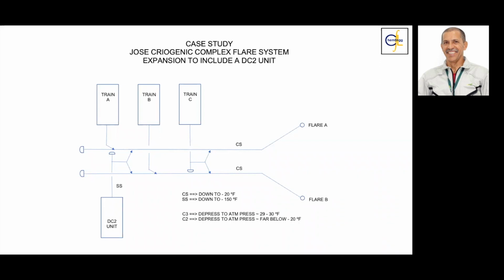Can you imagine that this material fails for any reason, and then the carbon steel cracks, and you have a leak of these light products in that plant? You cannot imagine the emergency or the problem that we would have. So this is another lesson we learned in this project, that is dealing with material selection.